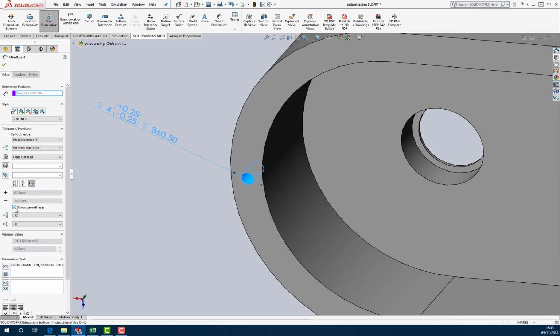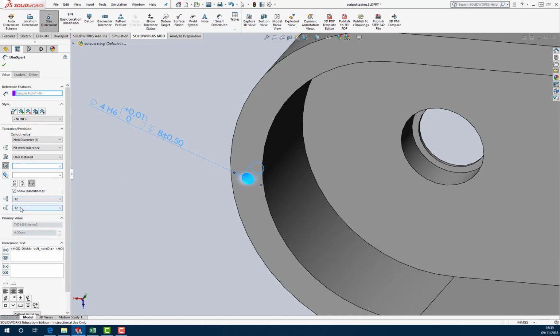We're going to put the tolerance in parentheses, and we're going to set the hole fit to give us an interference on the pin. If we went with a normal hole fit, which would be something like an H6, just going to increase the significant figures on the tolerance. There we go. We'd have up to 8 microns oversized. So our M6 dowel would be a very loose transition fit, not really what we want.